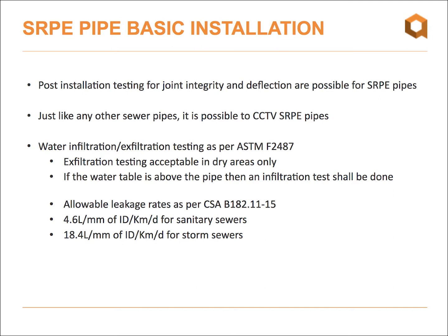Obviously, the exfiltration testing is acceptable in dry areas only. If the water table is above your pipe, then an infiltration test is required. Again, if you look at the requirements of the standard, CSA B182.11, the allowable leakage rates are 4.6 liters per millimeter of ID per kilometer per day for sanitary sewers, and 18.4 liters per millimeter of ID per kilometer per